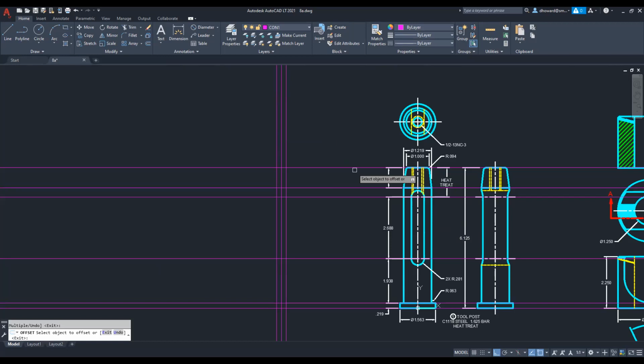And then the outside, again, the offset was just 0.25. So from the center out in both directions, 0.25. And you can see those lines are pretty close together, as they should be. It's basically the difference between those lines is the thickness of the thread itself, the little triangular shape. Okay, so the next offsets we have are the